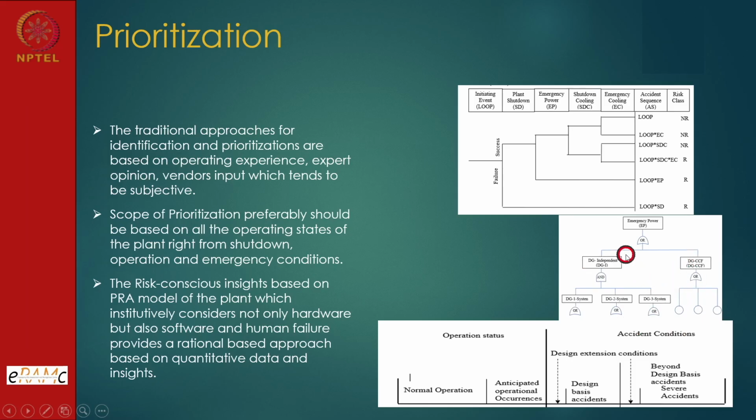So when we revisit the PRA model, we have to see the spectrum of that modification for normal operation as well as accident condition. Since we are talking here about an anticipated operational occurrence, it keeps happening, once in a year, or once in 2 years, or it could even be once in 6 months.